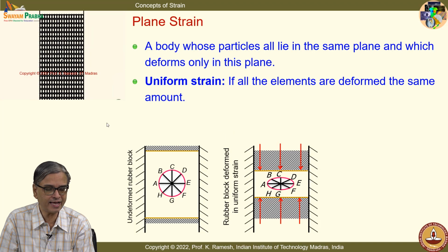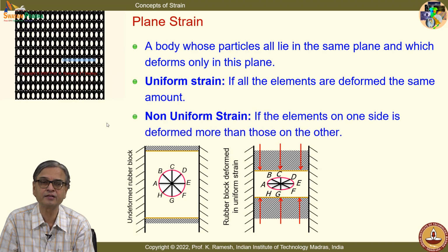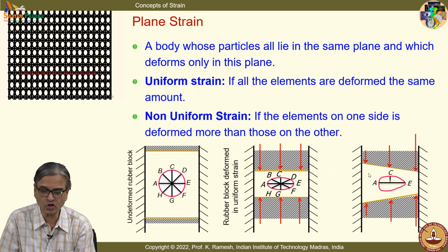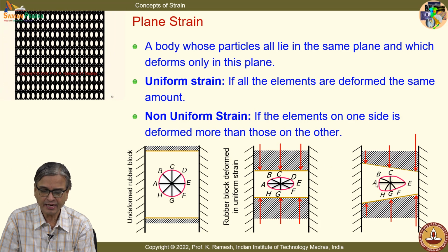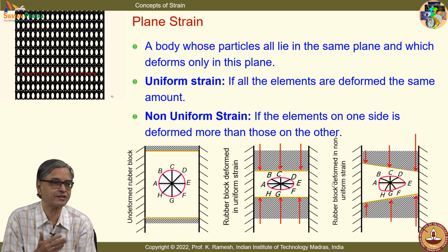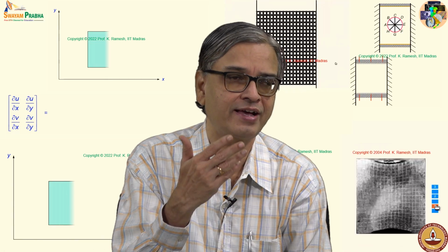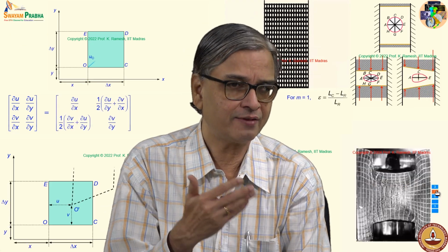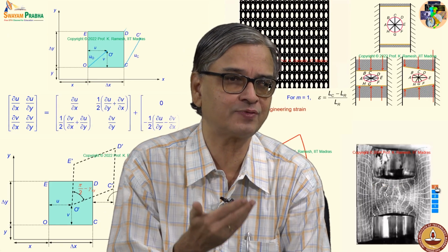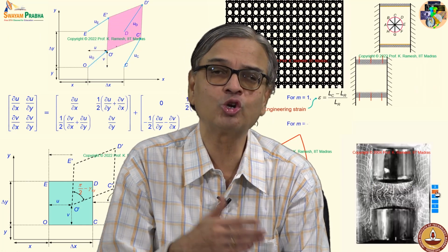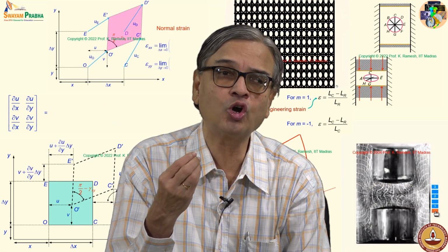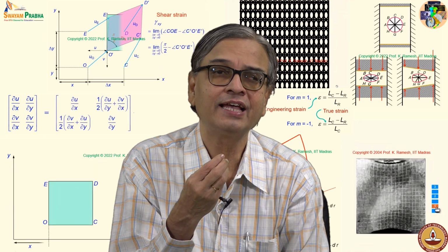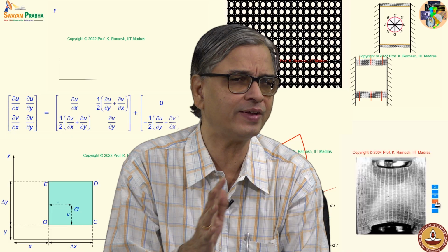And suppose I have a non-uniform force applied, you can have a very distorted shape, and you need the mathematics to evaluate the strain quantities. We have seen you have axial strain as well as shear strain, and we also saw that there is also rigid body rotation. We have determined the expressions in strength of materials very comfortably.